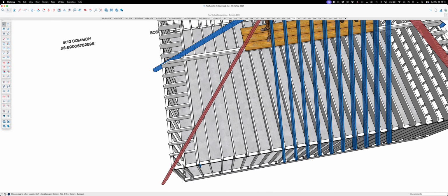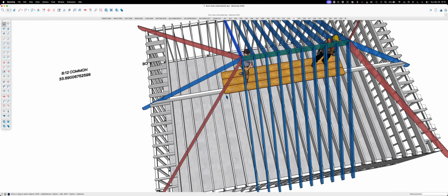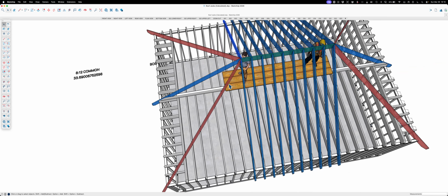But the more you aim for absolute true mathematical perfection, the more this structure will true itself. What I mean by that is if you know how to calculate all the jacks correctly, then they'll line up across from each other on a common roof. And if you trust that your numbers are correct and your jack's not quite fitting, well, then you bend the hip, or maybe the hip's got a big sag in it. You'd run a string and then brace it up vertically and then get it oriented left and right.